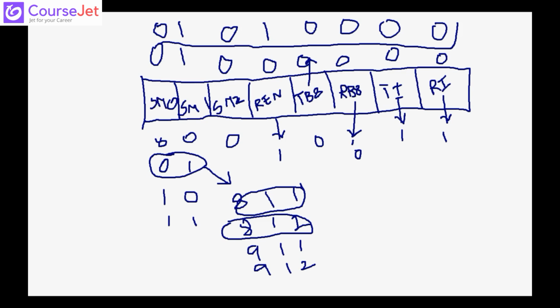We will see that later, but as of now you just need to know how to load this value of -3, or sorry, not -3, 3. As I said, you have to divide this by 3, right? You have to divide 28,000 by 3. So how will we load that into the timer register? Either you load -3, what is -3? It is equivalent to FD.